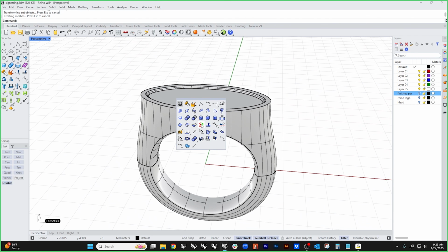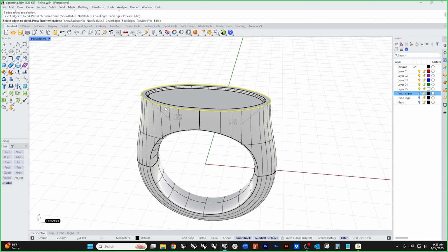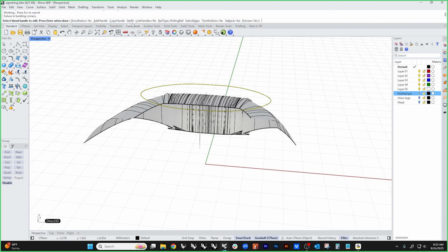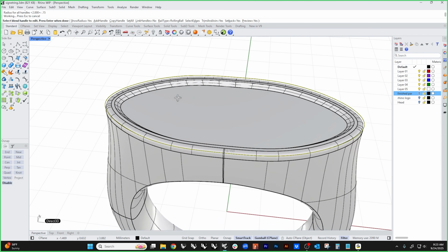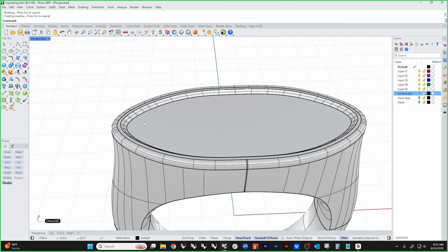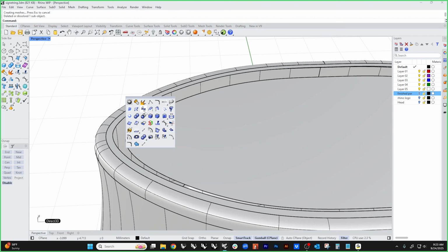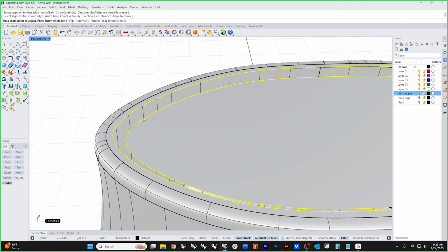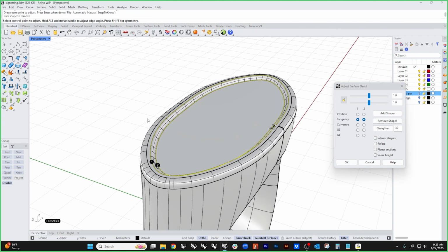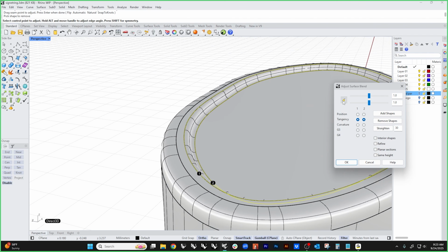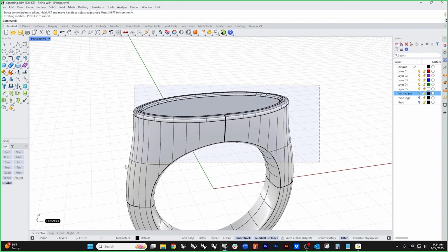And then if we wanted to, we could then do our blend edging. And maybe we even want to replace this with a blend surface, so that it's got your fillet thing going on there. And then we say OK.